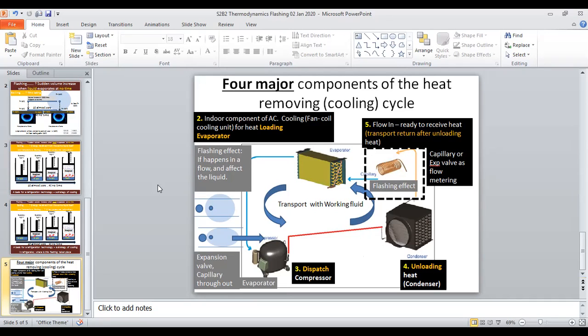That's why it is very important in evaporator designs. Also when you do the charging or fill the refrigerant, if it is overcharged the pressure drops, leading to this kind of situation. So to understand everything, knowledge about this flashing effect is important. Okay.